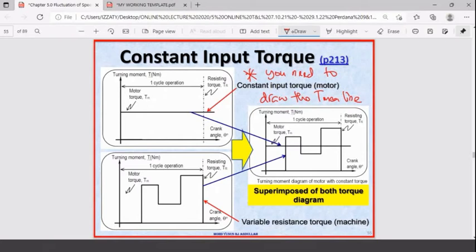Okay, this one, for example. When you've been given this, then you construct this one and you will have a line of the mean. This area represents all the energy from the power source, which will be the motor here. So the motor provides the graph represented by this one. You calculate this one, it gives you the torque and theta from the motor.